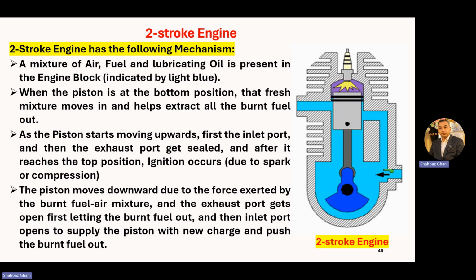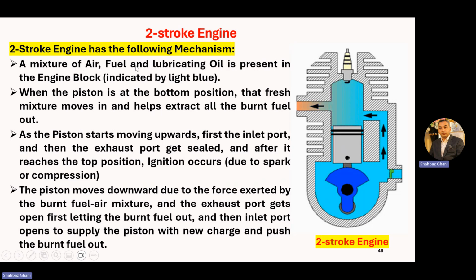Two-stroke engine. Two-stroke engine has the following mechanism. A mixture of air, fuel, and lubricating oil is present in the engine block indicated by light blue. This is your intake. From here we are getting air fuel mixture. Air fuel mixture is coming here. This is your crankcase. Crankcase is filled with oil.